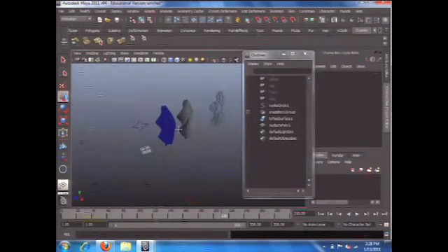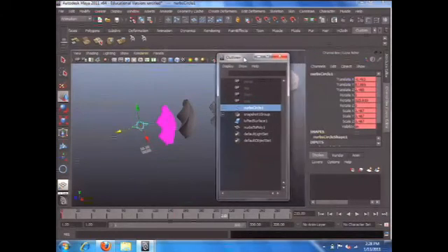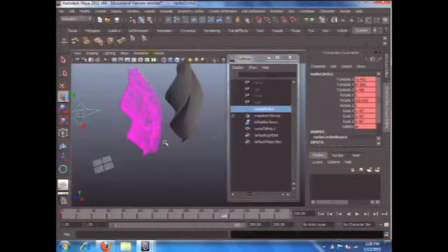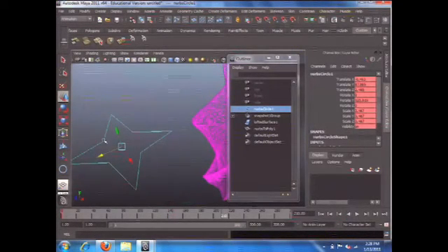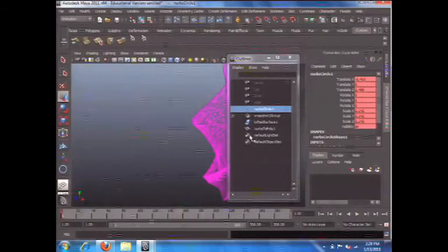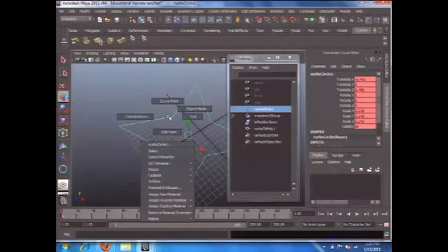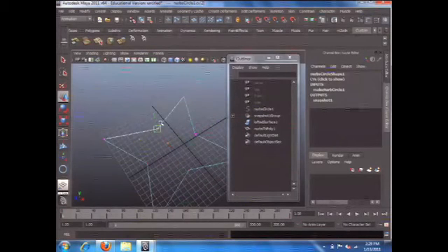So here's a question. We know the animation can be easily controlled through these channels. Can you manipulate animation at the component level? In other words, I'm not going to just keyframe XYZ translate, rotation, and scale. I want to manipulate individual points. So for example, in this case, I would like to manipulate every single point. Can I animate the movement of these points? So each level of the skyscraper, the shape is different. Can I do that? All right, the answer is yes, absolutely.